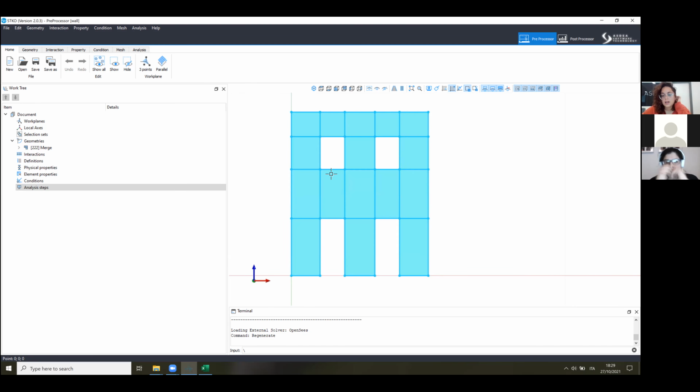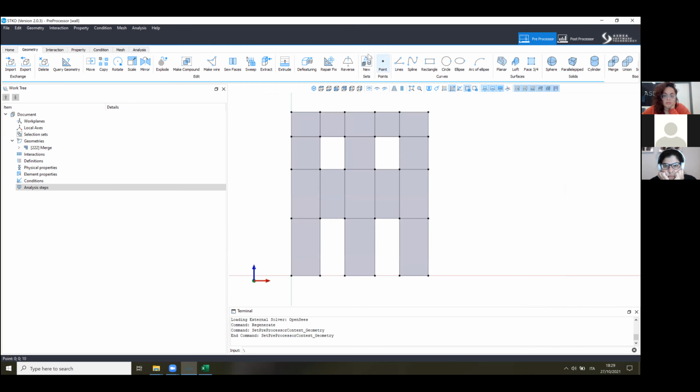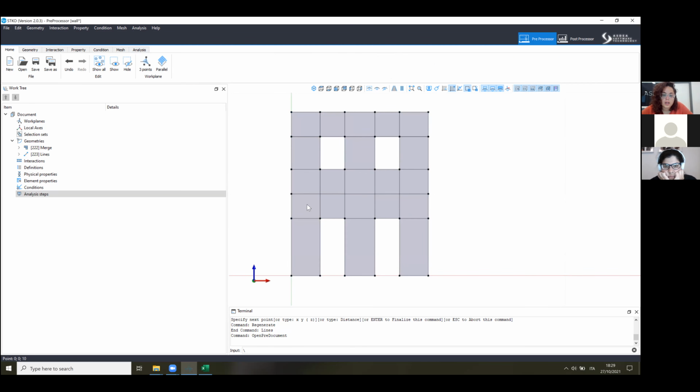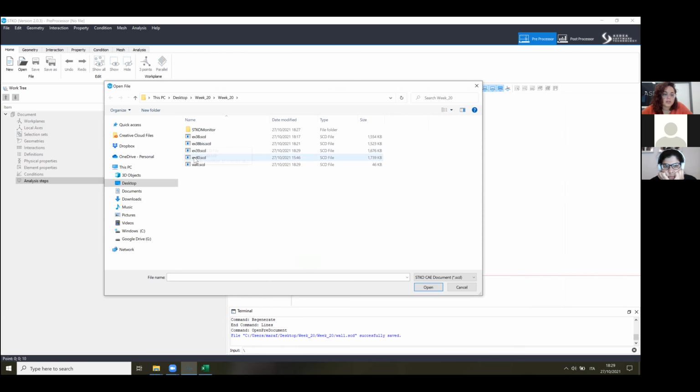In this case, you can create a link here if you have a rigid diaphragm, but your spandrel can be as high as this double height, even if your diaphragm, let's say the floor, is here. Yeah, exactly. But then you can create elements this height because of course they collaborate, if it's a masonry wall, and then you have rigid links. So to simplify this kind of structure, I created this model here.